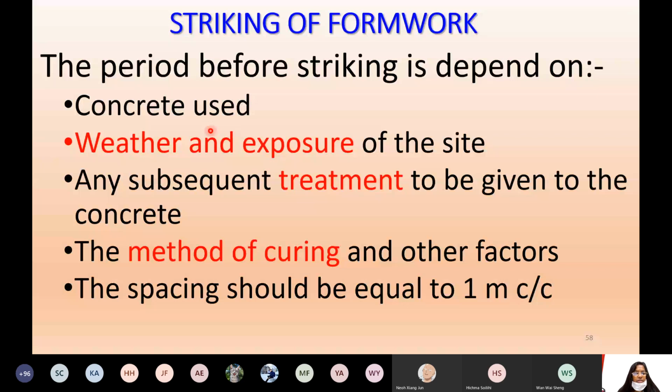So the duration depends on the concrete used, right? The grade used, the curing time, the weather, and the exposure of the site. The holding time for the formwork will depend on these weather conditions. If it is cold weather, you have to prolong it, not 24 hours, but 24 days or 30 days for the slab. You have to extend it.